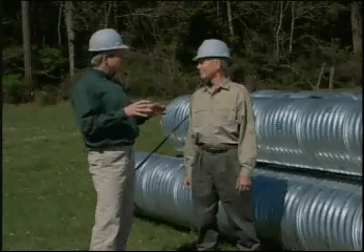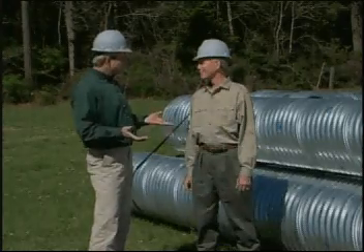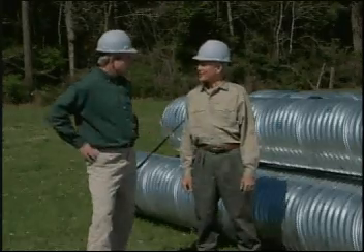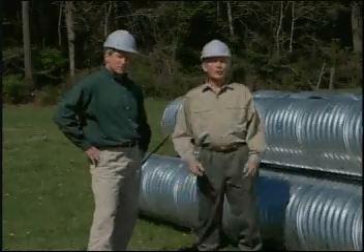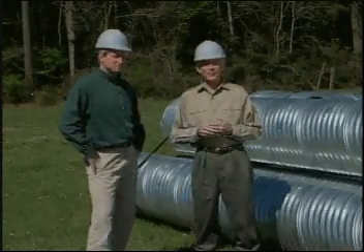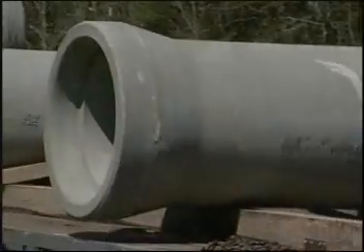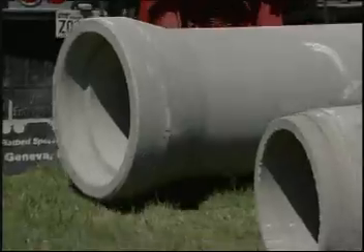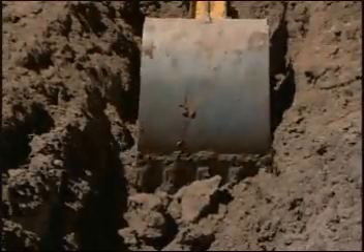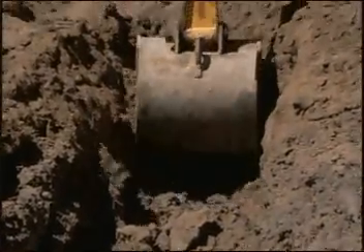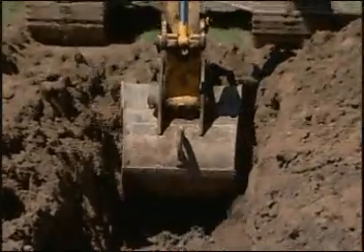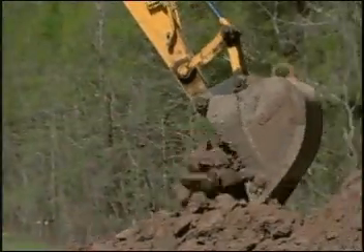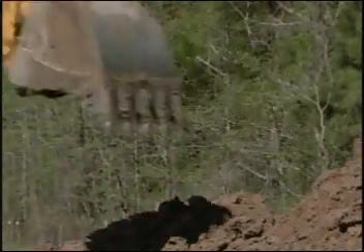Well, won't he also need to provide additional fill or bedding material and labor to meet the engineering specifications for this support? In most cases, that's right. For all pipe materials, he pays for the conduit delivered to the job site. With concrete pipe, the manufacturer provides the required structure in the delivered pipe. With flexible pipe, the contractor or owner must rely upon the installation crew to build the required structure in the trench with the proper embedment materials, proper placement of those materials, and careful compaction.